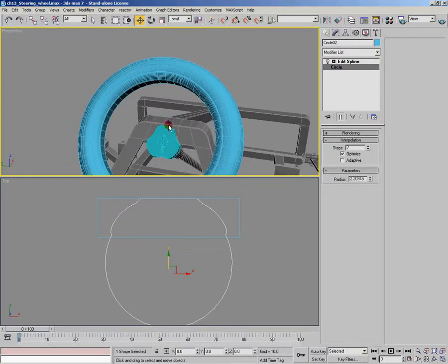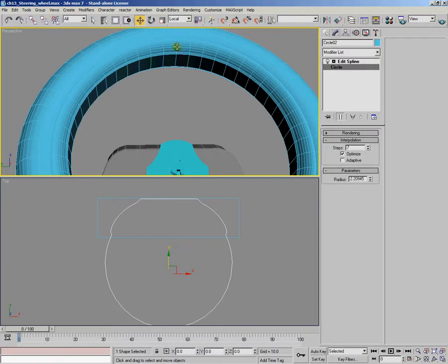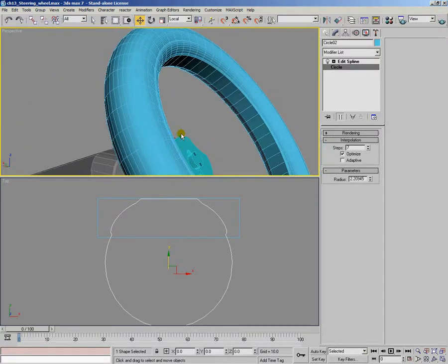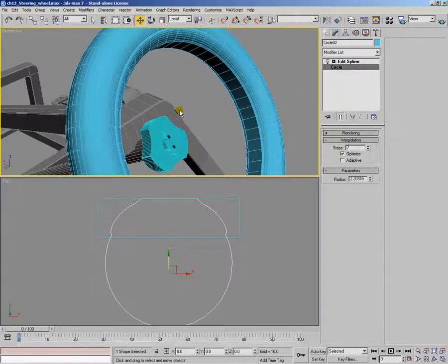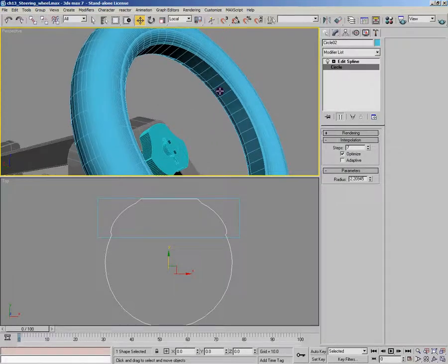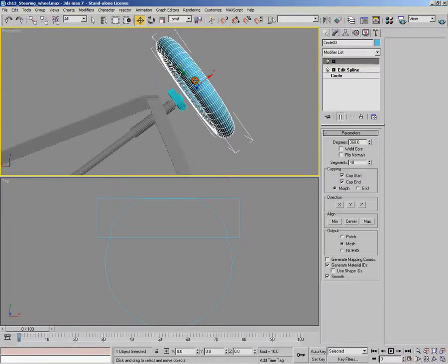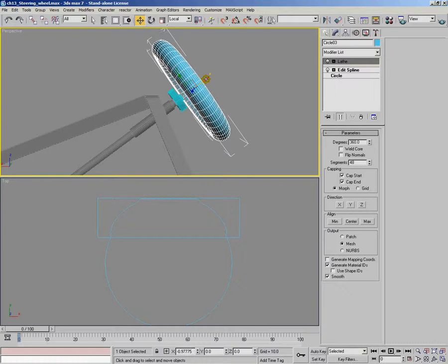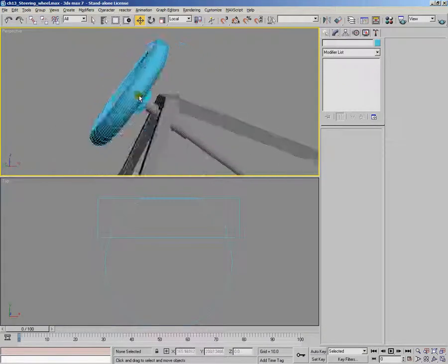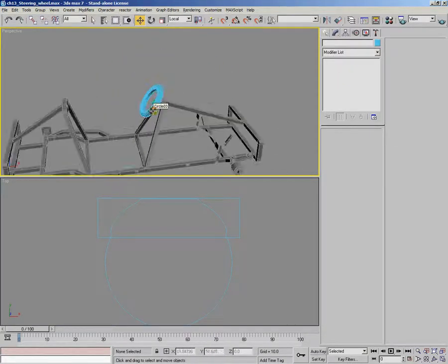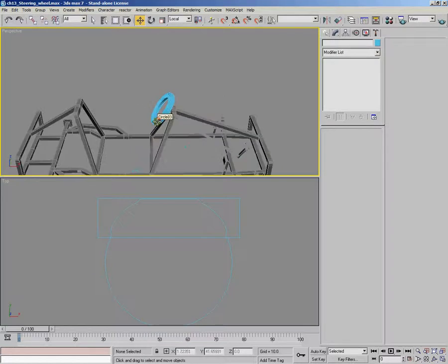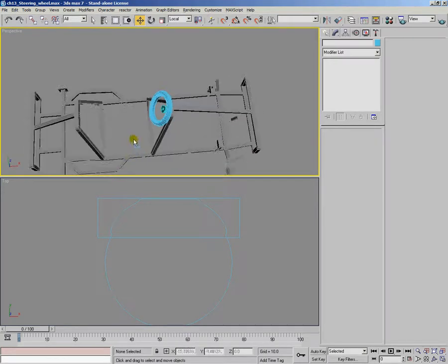What I'm going to do is actually loft those because I want it to be curved, and I don't want it to be a straight line between here and here. So extrude isn't really what I want. And maybe at the moment this is a little bit far out, so we'll just bring this down a little bit. And so we know that when we create a loft, we can use the instancing features of it to make our modeling life a little bit easier.